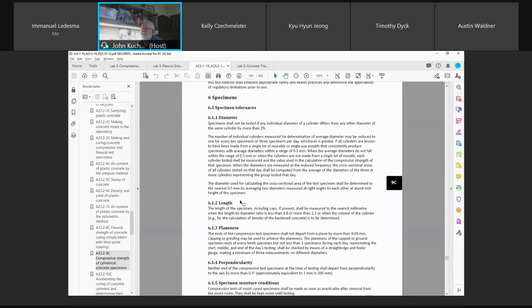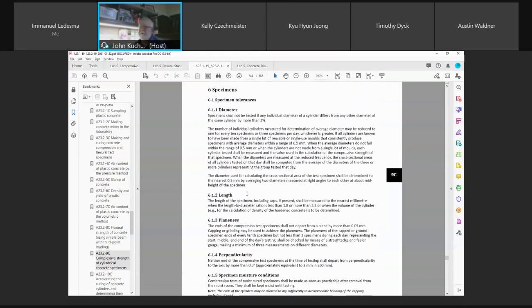I used to cap cylinders before we ground. Sulfur, though, is very hazardous. It stinks. It's a fire hazard. I burnt my wrists one time because I was using hot molten sulfur. I was capping, putting it in the jig to get that nice round cap. It slipped on me, splash, sulfur went up, and burnt my wrist, and I couldn't get the sulfur off because it starts to cool right away. So as it's cooling, it's burning you, and then when it cools, you can then peel it off along with some skin. So sulfur isn't ideal.